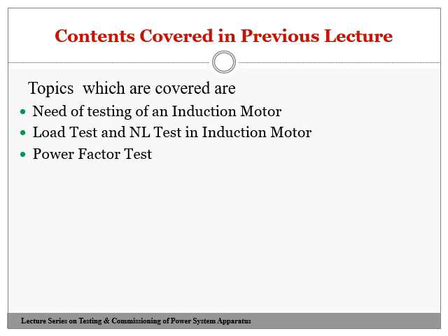Then afterwards, we went through a no load test. In that case, we found the no load current, the no load power factor, as well as the core losses that exist in an induction motor when it is operated at a particular no load condition. That test is also called the rated voltage test.